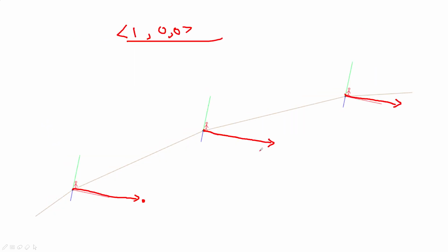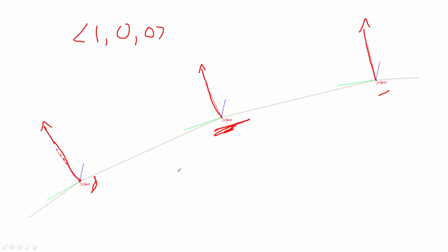Now this is very different from this other cylinder that we have. Here, all the first degrees of freedom, the translations along the x-axis, were all parallel. They were going to the right in this image. But for this new set of degrees of freedom, the x-axis, if you will, is going in the radial direction. So this is very important for us. Whenever we define that orientation vector, it's being observed in these degrees of freedom coordinate systems. You can imagine that there are different stick figures, different persons at each coordinate system. Each one of them is going to be observing this vector differently.